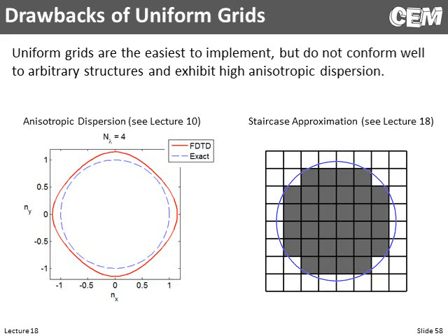And if we actually have a curved boundary, at some level we're going to have to make some kind of staircase approximation. So if we wanted a perfect circle in this Cartesian grid, we'd have to fill it in as best as we could to approximate the circle, but it's not perfect, and that's called a staircase approximation. If our cells are small enough, it's a pretty good approximation, but it's forcing us to use pretty high grid resolution, which will slow down our codes.